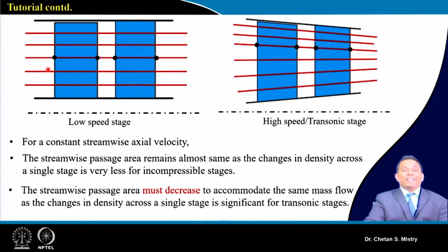If you have a smaller number of stations, then it will cause some difficulty when you start making the solid model for that blade. And it may be possible that you will not have great control over loading or the expected performance from a particular aerofoil at a particular span. So it's preferred that you go with more stations.